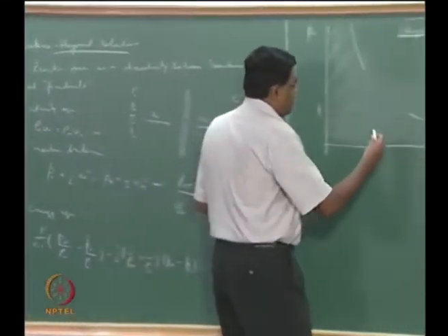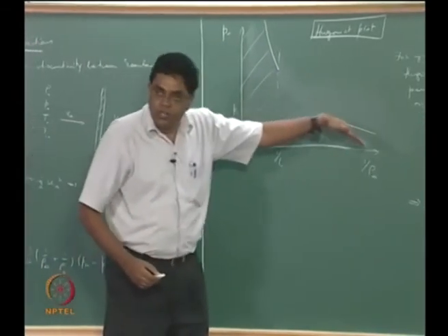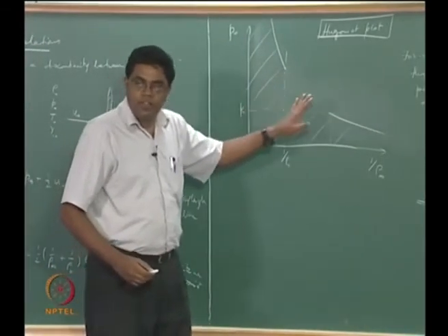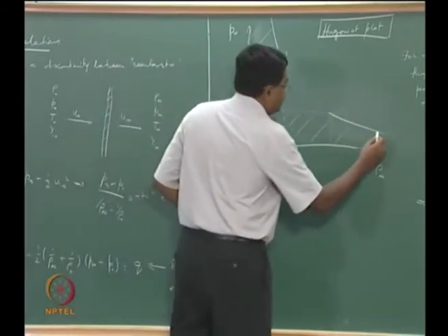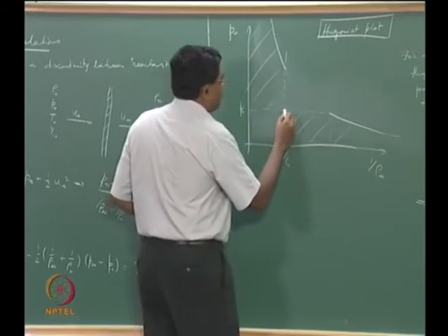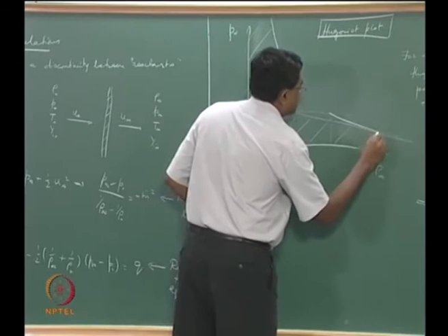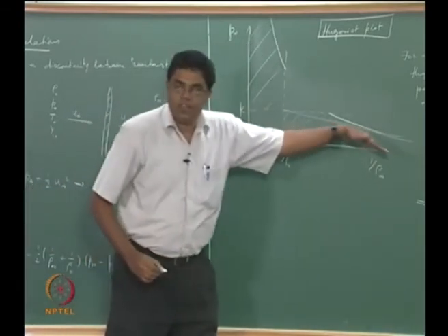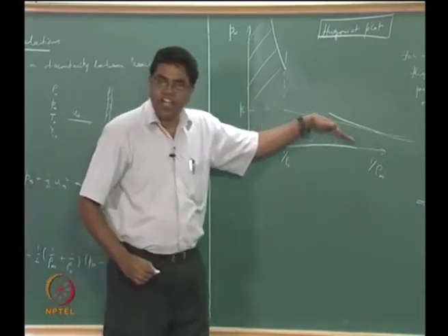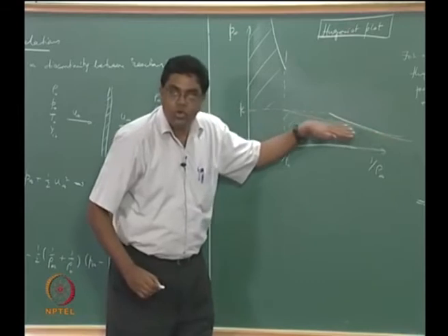So you now have one branch of the Hugoniot that is now beginning to correspond to waves that are moving kind of very slowly, okay, and the fastest wave could possibly have a slope that is tangent to this at this point. That's the fastest wave that is possible. That is the highest m dot that this branch of your Hugoniot will intersect.